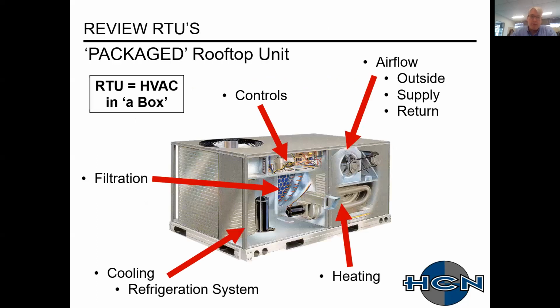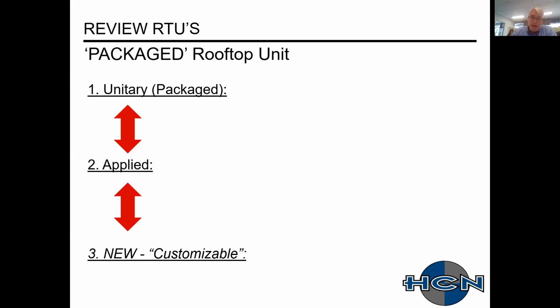All right, so just a quick review. Rooftop units, they're great. HVAC in a box. You get controls, filtration, your cooling with the DX refrigeration system, different options for heating, and then you have all your three air streams covered: outside air, supply air, and return air.